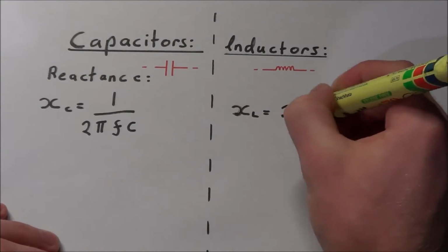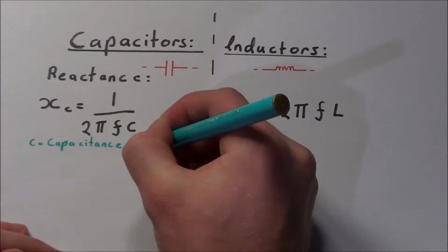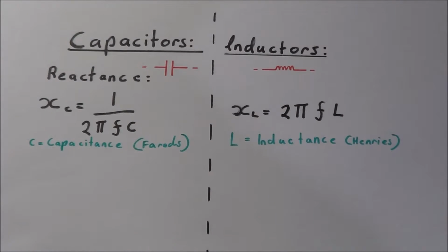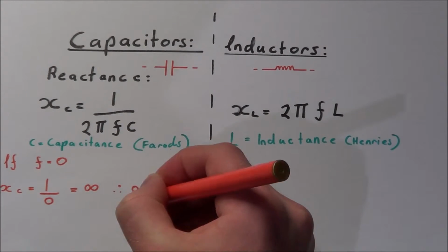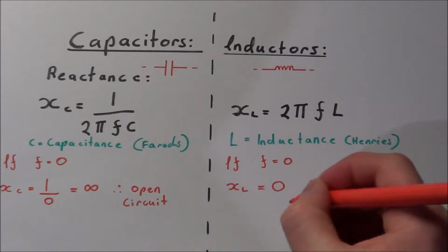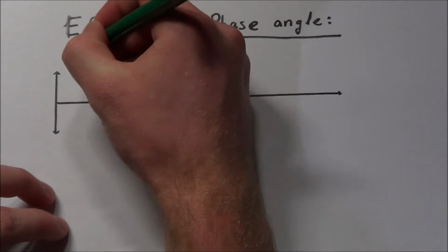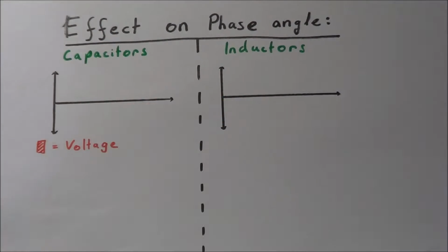In the equations, if frequency is set to zero, reactance is equal to infinity for a capacitor and zero for an inductor, which is how capacitors and inductors act in circuits when they reach a stable state, open, and closed or short. The fundamental concepts of analysing both series and parallel circuits are the exact same in AC as they are in DC.